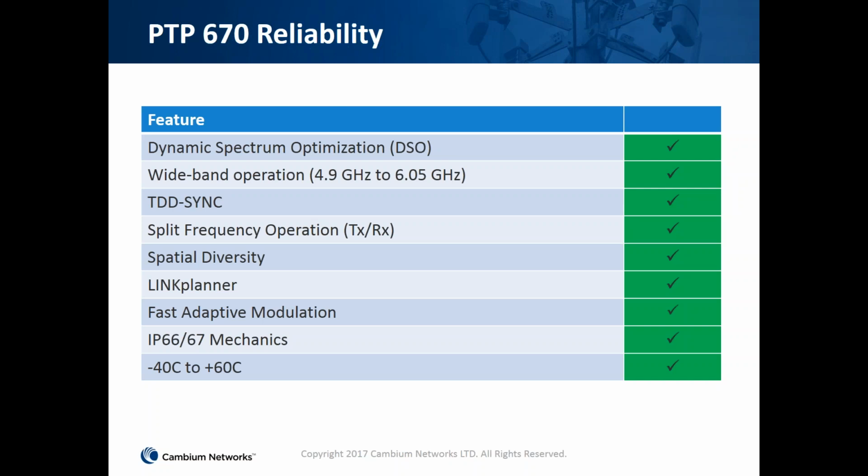We have a fast adaptive modulation, which I spoke about earlier. That's due to changing of adaptive modulation from 64 QAM to 16 QAM based on noise, or maybe increasing it once the noise fades away.